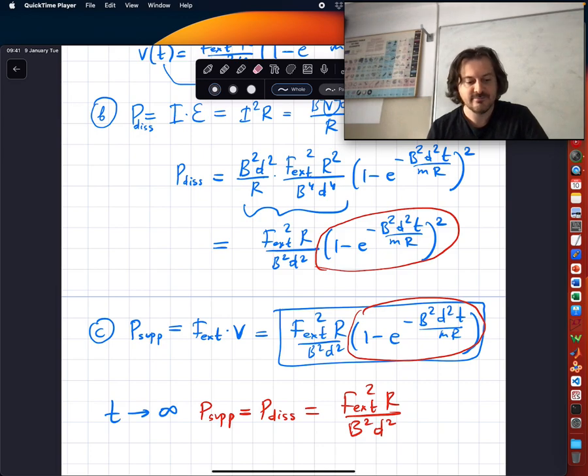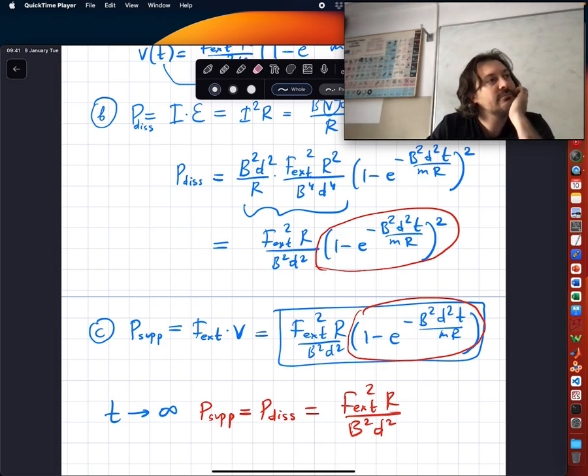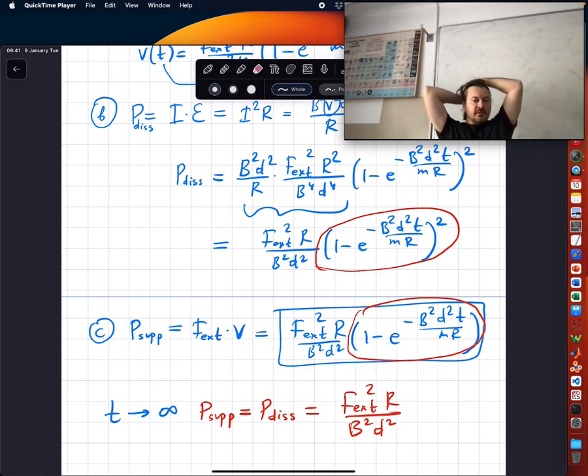Okay. Can we consider the force caused by the current, multiply it with v, and call that the dissipated power? That's a good point. Yes, you can. So if we take the difference, F external times v minus F induction times v. Yes, exactly. So you can find the surplus of power by finding the total force times the velocity.